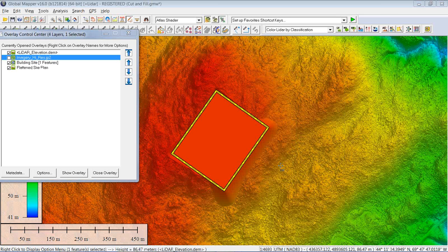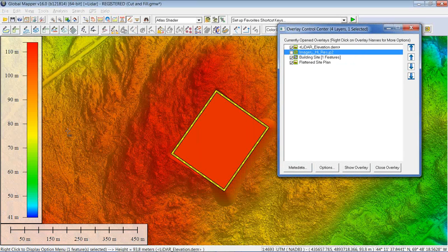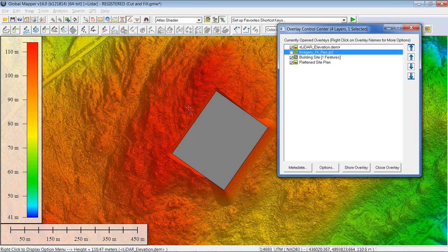Now, my area is selected, so you're not actually seeing the area feature itself, which allows us to see the modified terrain surface. One of the things you'll notice is that it is a solid color. As we would expect, it's a solid color because it represents that 106 point whatever the decimals were meter value right here, and you can see that's now a consistent elevation. I'll go ahead and deselect that.